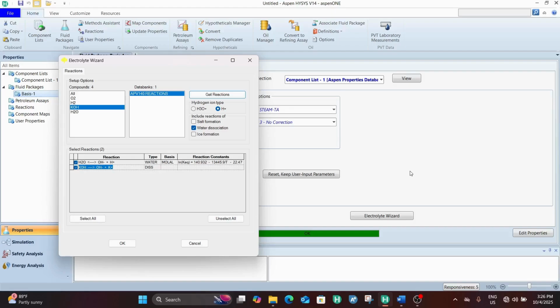And to do that, water needs to conduct electricity, and water in its natural form is a poor conductor of electricity. And as such, we introduce a salt, which is potassium hydroxide, to improve the conductivity of water. With this, it makes it a better conductor of electricity, and it improves our efficiency for producing hydrogen gas and oxygen gas in the process. So that's the reason why we're having potassium hydroxide in this process. So with this, we have generated our reactions.